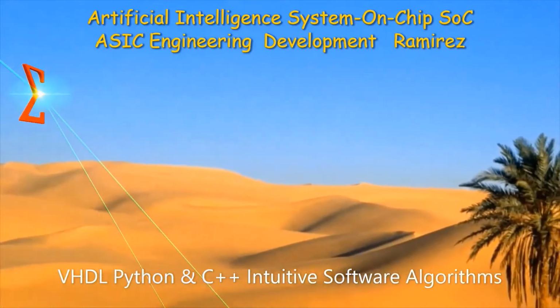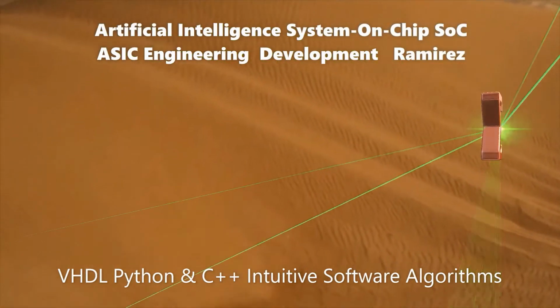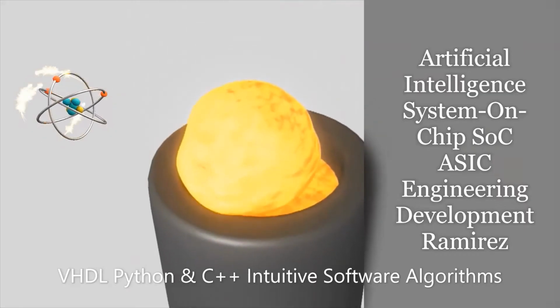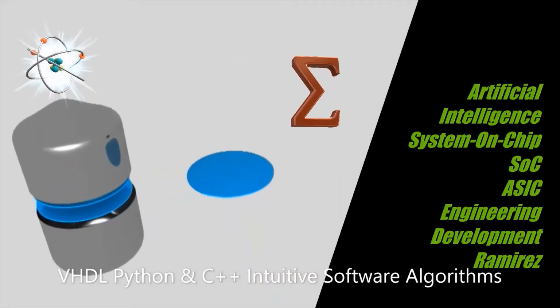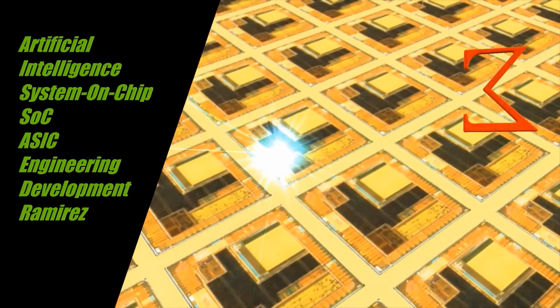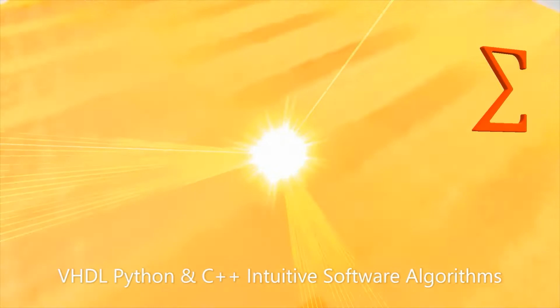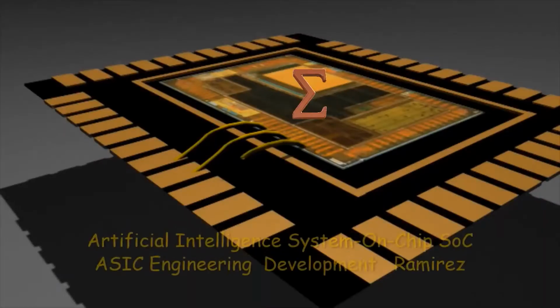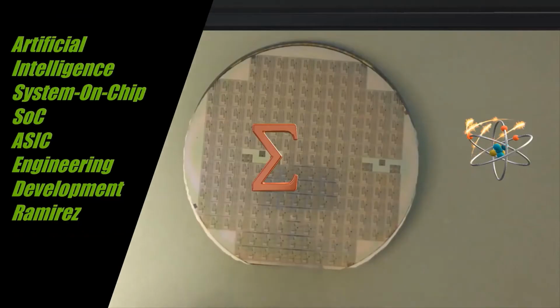Blank wafers are put through 20 to 40 steps to create pattern wafers. These pattern wafers are then tested with a wafer tester, and a map of the good parts is made. Afterwards, the wafers are diced into dies.